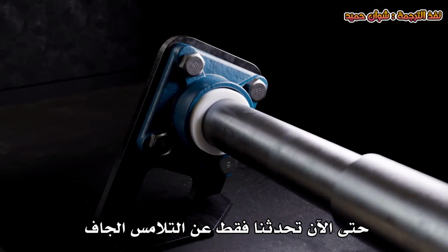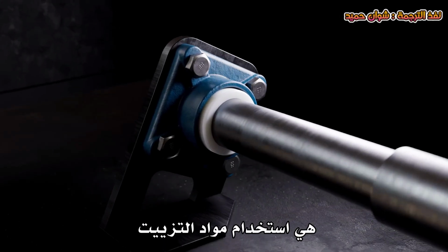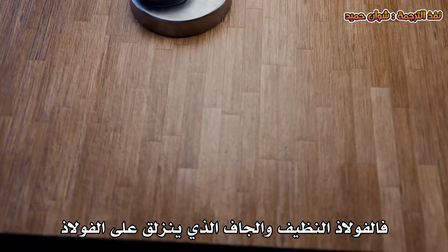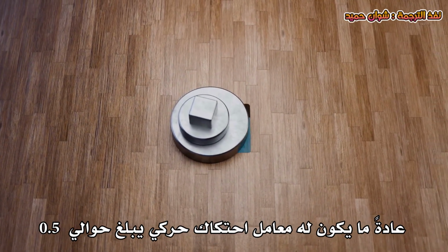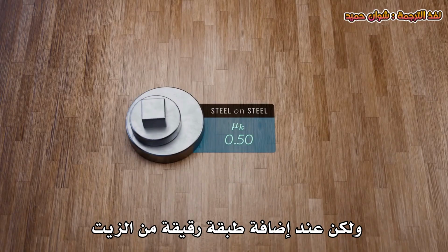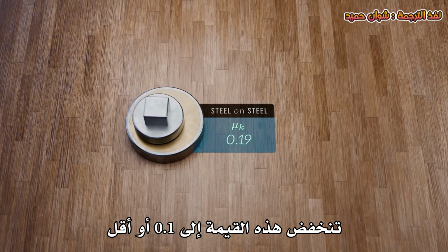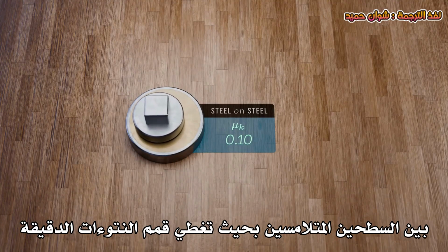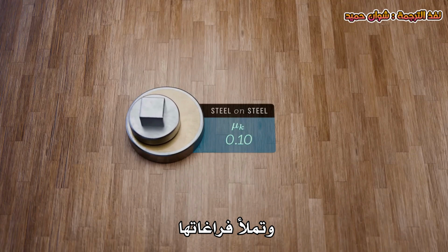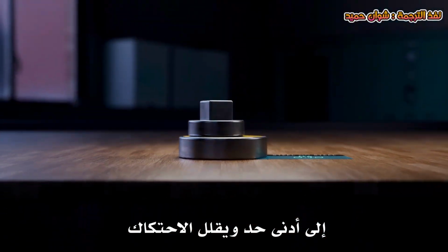So far, we've only talked about dry contact, but one of the best ways to reduce friction is the use of lubricants. Clean, dry steel sliding on steel typically has a coefficient of kinetic friction of around 0.5, but add a thin film of oil and it drops to 0.1 or less. Lubricants work by introducing a thin film between the two contacting surfaces, coating the peaks and filling in the troughs of the asperities. This minimizes mechanical interaction between the surfaces and reduces friction.